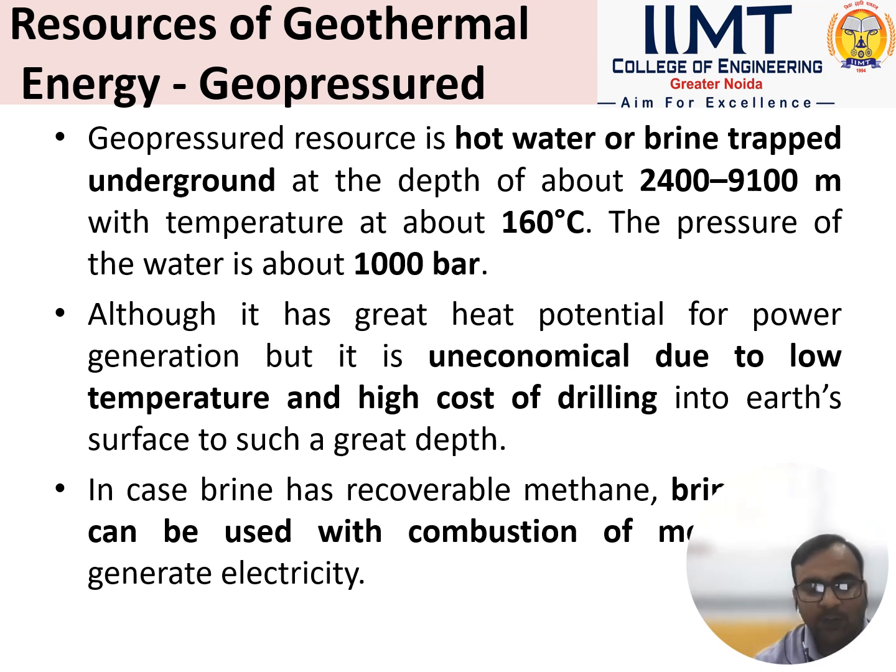It's available at high pressure, so obviously we'll be getting higher energy. But it's uneconomical because of the low temperature. Superheated water has high temperature, so at high temperature we'll get higher energy. Here the temperature is low, and we have to drill a hole, so there will be a cost. If by putting that cost we are not able to extract sufficient energy, then it is of no use to us. So it will be uneconomical due to low temperature, and obviously the cost will be higher.